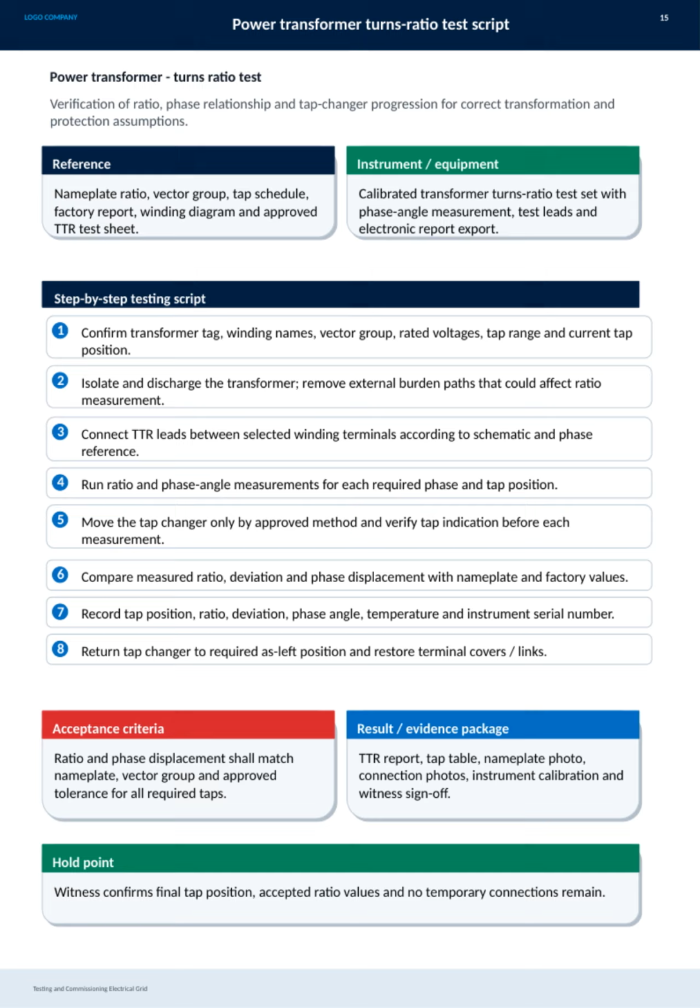Finally, the hold point calls for a witness to confirm that the final tap position is correct, the ratio values are accepted, and that no temporary connections remain. This thorough procedure ensures the transformer operates safely and reliably within its design specifications.